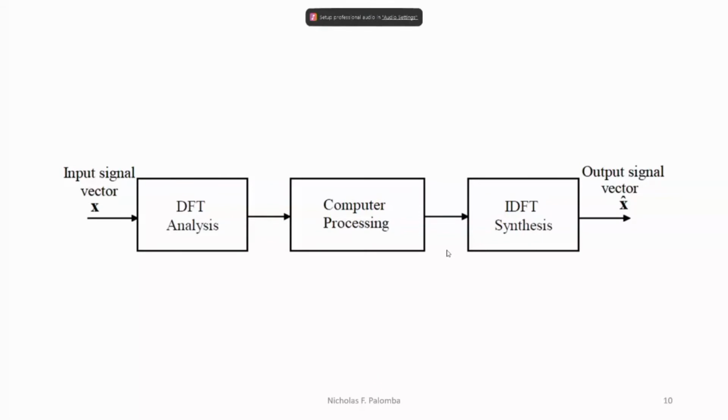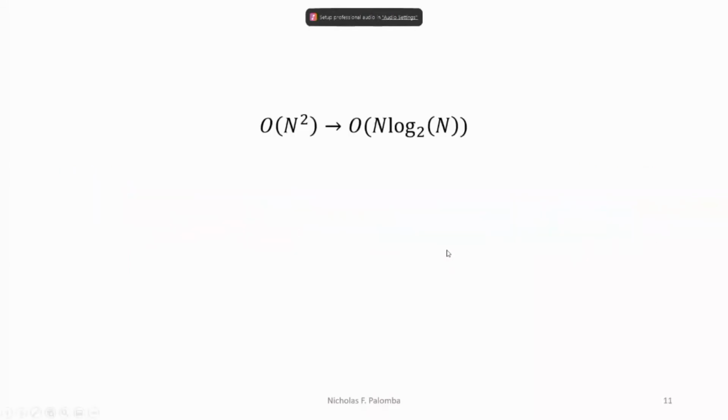And you also know that the fast Fourier transform, FFT, is an algorithm that computes the discrete Fourier transform or the inverse. It manages to reduce the complexity of computing the DFT from O of n squared, which arises if one simply applies the definition, to O of n log n, where n is the data size. This is because the DFT requires n squared multiplications and n squared minus 1 additions to compute the discrete frequency spectrum, while the FFT only requires n over 2 log n of each.